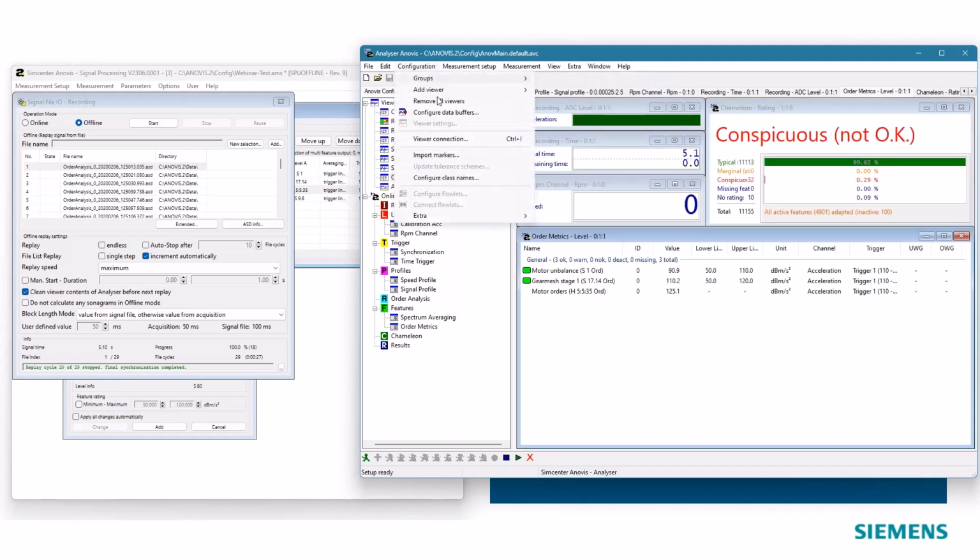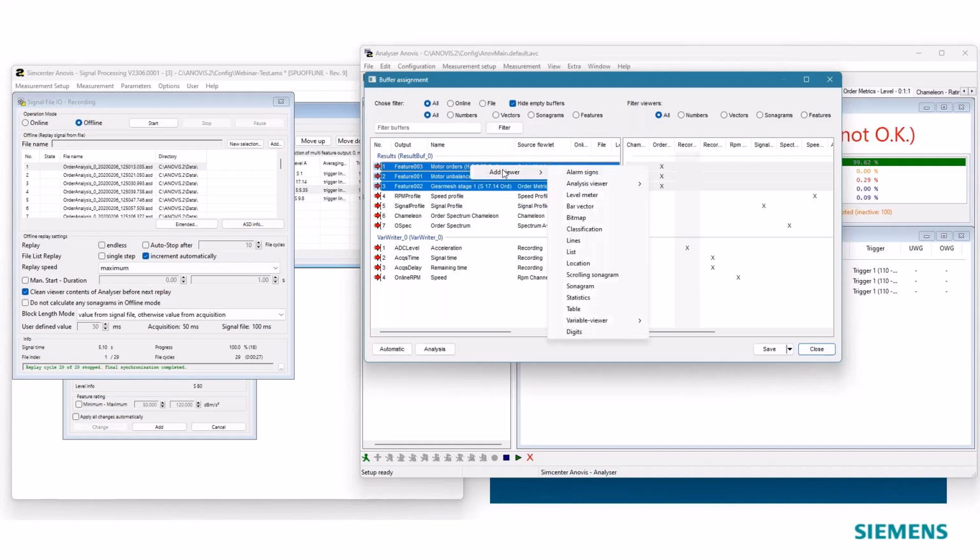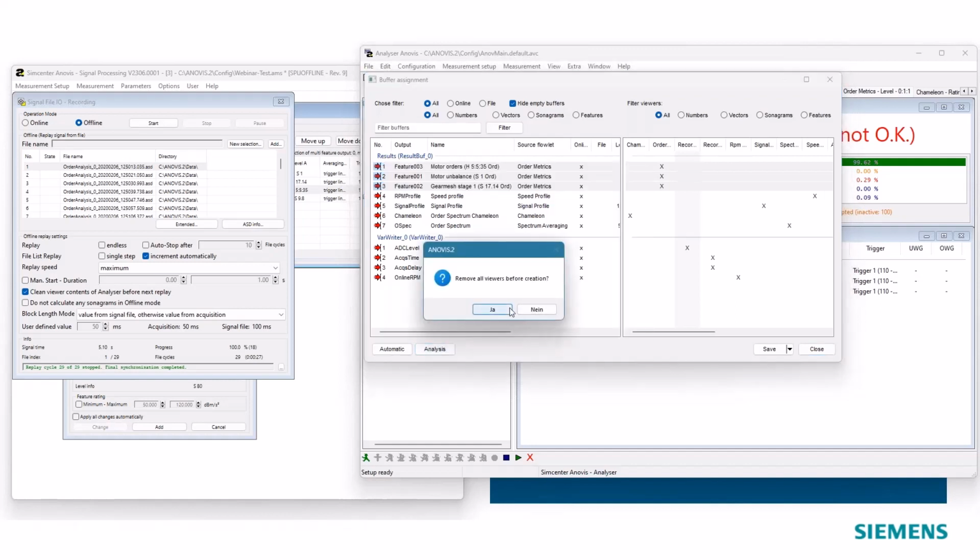And in that case, it was actually not just a single order like the first order and 17th. It was 5 and its harmonics. That's interesting. Yeah, and I'm not really sure if the fault shows a slightly different representation, if it will be again order 5, or I assume sometimes it can happen that order 5 distance is too low and I have to look at order 15. To avoid this, I sum them all up together, and then I'm sure that I catch it, even if it looks a little bit different.